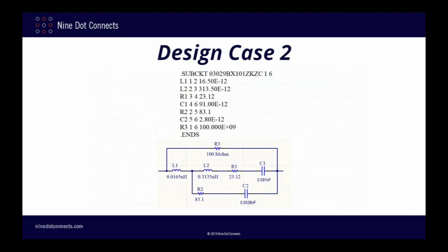Unfortunately, the real world is messing things up for us again. While it is true that an ideal capacitor acts as a short at high frequencies, real-world capacitors are not quite as well behaved. As we see in this slide of a SPICE model of a capacitor, a real-world capacitor also has parasitic inductance associated with it, and as we know, inductors act as open circuits at high frequencies. This will tend to negate the benefits of the stitched capacitor as a current path.